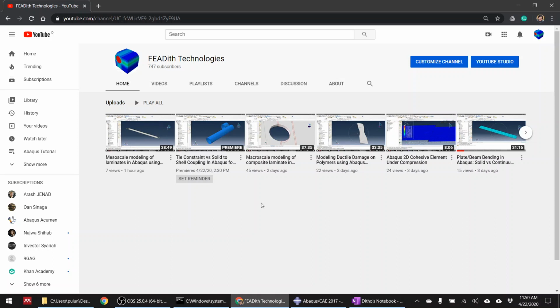In today's video, we are going to continue the previous video on the mesoscale modeling of composite laminate in Abaqus. In the previous video, we used cohesive elements to connect one ply to another, while in the video we are recording now, we are going to model the connection between plies using cohesive surface behavior. So instead of using elements, we're going to use a contact interaction that has cohesive behavior. So we need to set them in Abaqus under the module interactions.